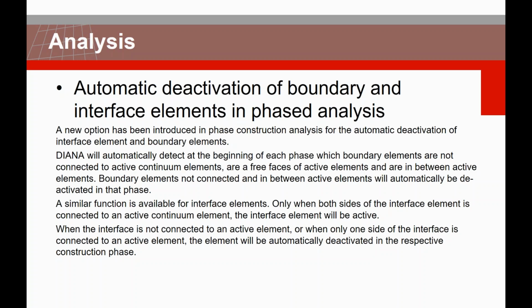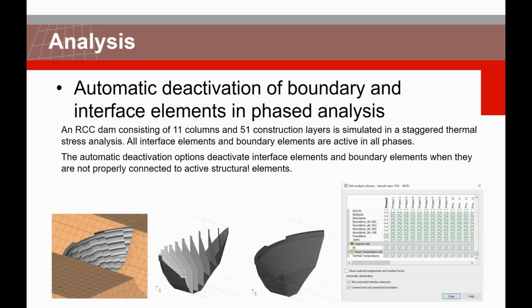And if you're dealing with the flow boundary condition, as you go through the construction and the matches between two adjacent flow boundaries, the program automatically deactivates that and makes it available for flow, basically convecting or passing the pressure from one block to another block. So this is very useful.